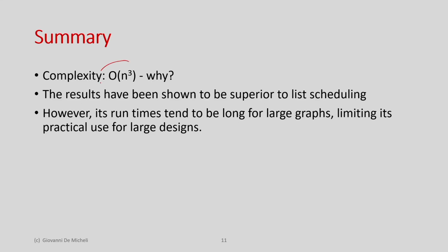But for this MRLC, whenever the latency bound is given, you want to minimize the resource. The idea here is that you schedule one operation at a time which has the least force. That means in every iteration I make sure I am increasing the concurrency in the minimum way, and hence my algorithm will give me minimization of resource. And we have seen that the complexity is order of n cube.